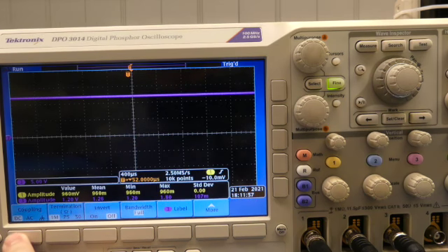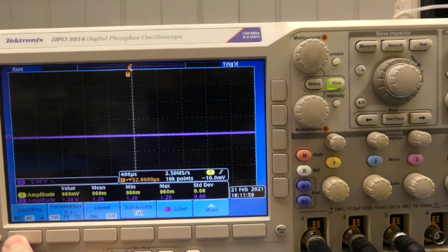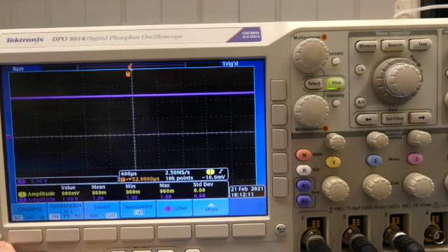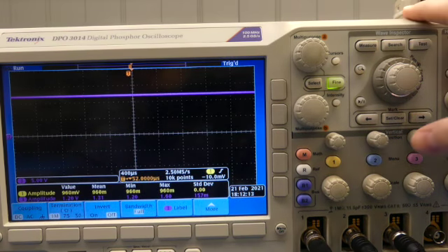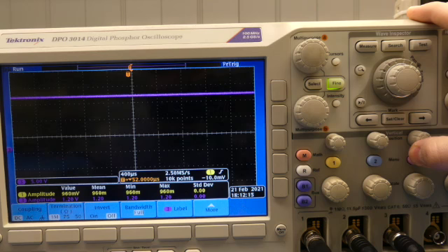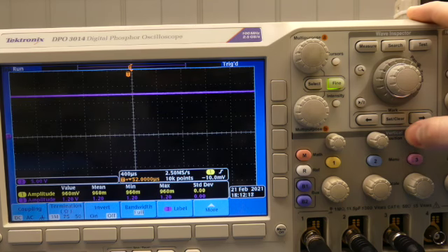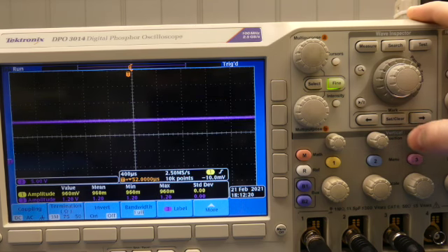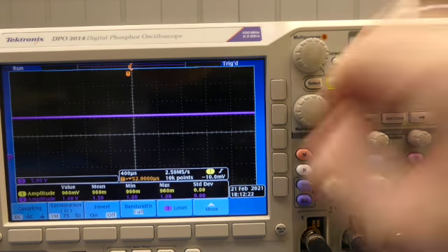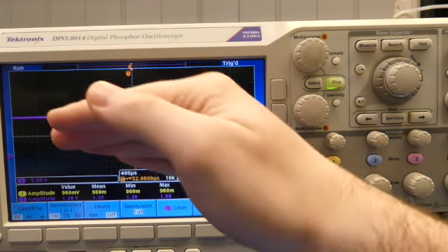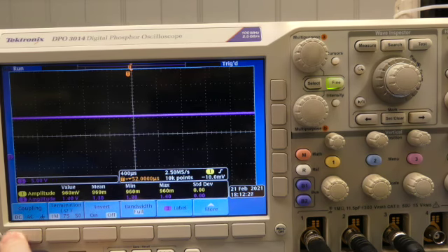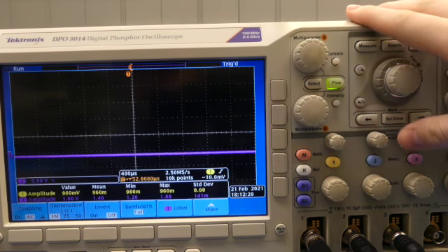If you turn on AC coupling, it will not consider any kind of DC measurement being read, right? So now if you say you have some kind of weird DC voltage that's really putting your waveform through the roof, and you can't change the offset to get the signal to go back down to somewhere where you can read it better, you can turn on AC to eliminate that, and it'll bring it back down to 0 or to wherever you have your vertical offset set to for that channel.